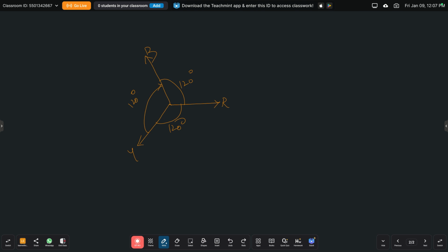When the three phase supply is excited, the currents IR, IY and IB are carried by the primary windings, and thus induce the fluxes phi R, phi Y and phi B. The central leg will carry the sum of all the fluxes, and the center leg combines all the legs of the core. Based on that, we have to represent it.